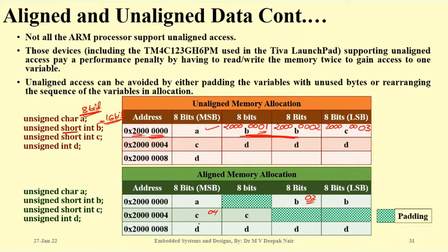So the program counter can point to these locations to access the data, but the stack pointer, to store stack related data, will never use these kinds of arrangements. That means SP, the stack pointer, does not support this kind of alignment. But the program counter allows you 02, 04, and so on.